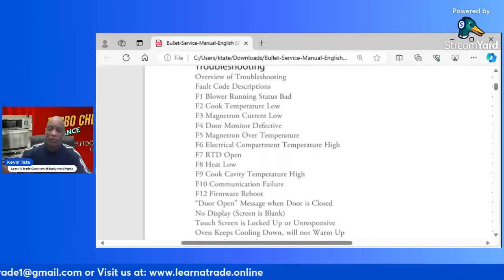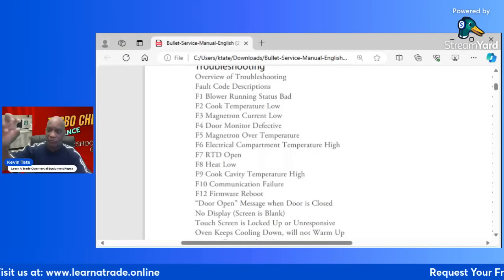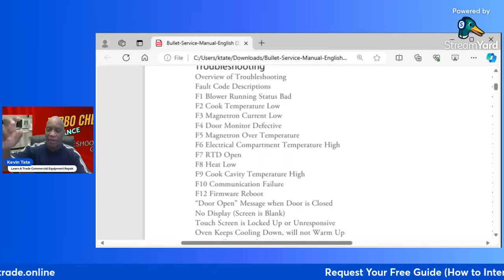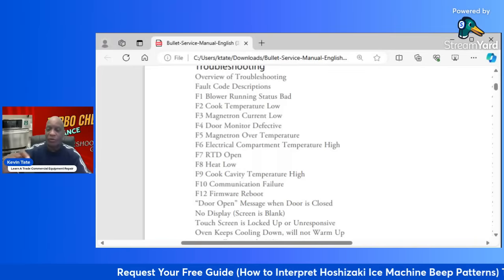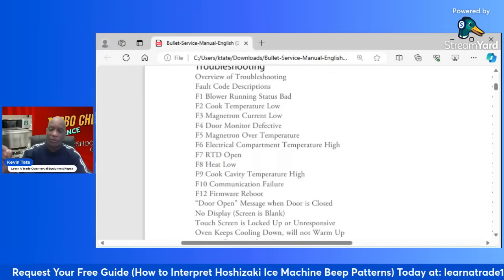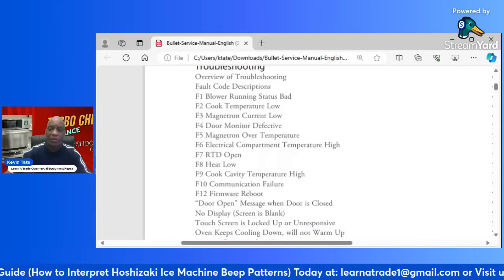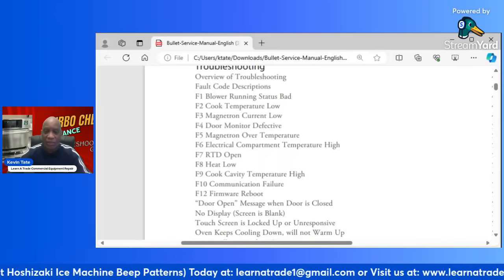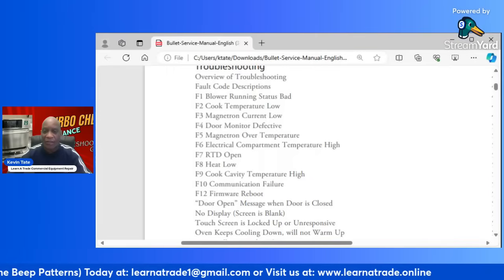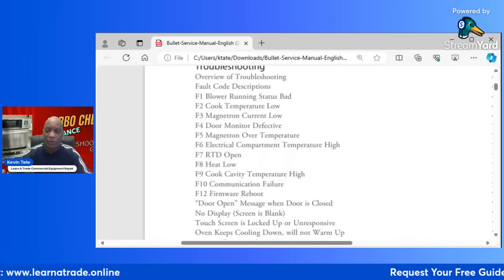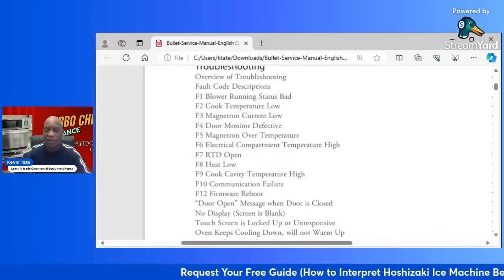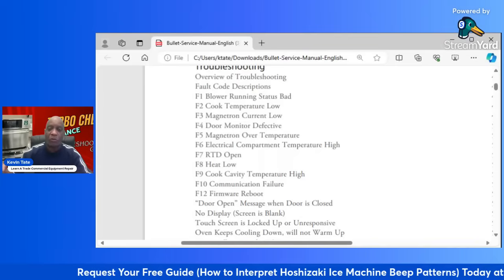And it has four wires going up, connecting the four terminals on the top part of the relay, and on the lower section of the relay, there's a four wire terminal that plugs into the bottom. Now, sometimes that relay goes itself, but a lot of times it's just that lower four wire terminal that has backed off, and it's not connecting well to the terminal of the relay.